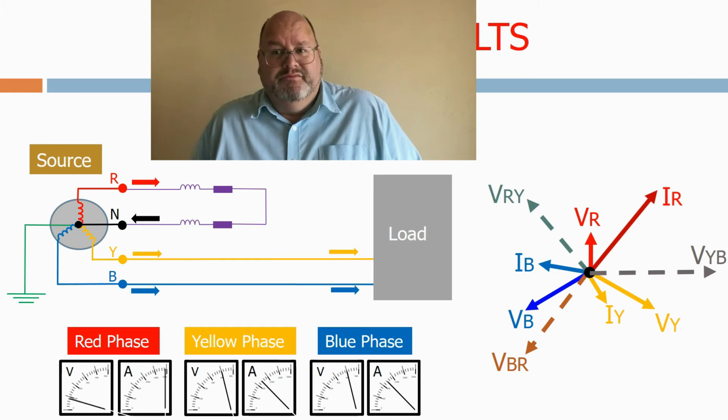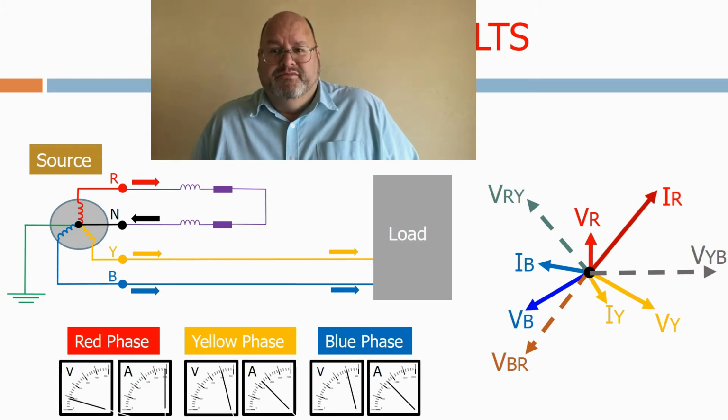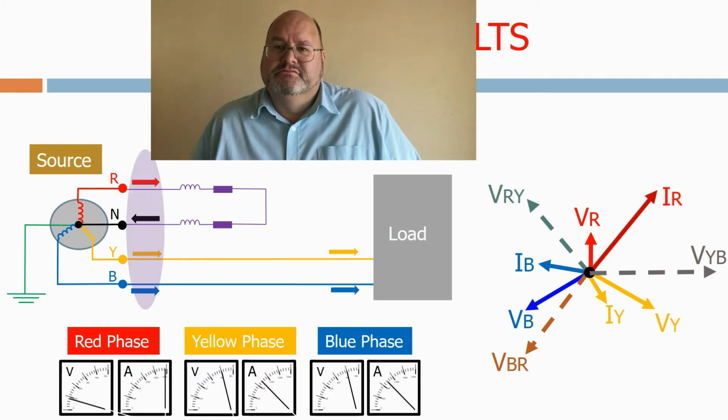The blue to yellow line voltage has not been affected and stays the same. The red to yellow and red to blue line voltages are both changed in their magnitude and angle, as the red voltage has reduced. If we now try and summate all the currents, it will still equal 0, as although the currents have increased, there is no current leaking out of the system.